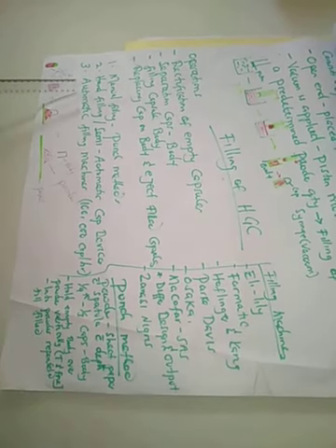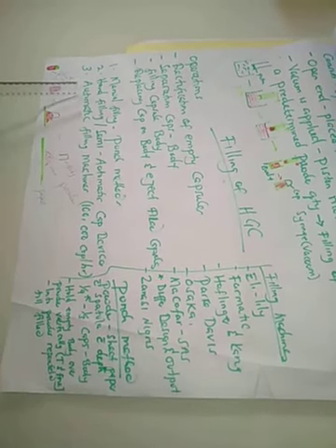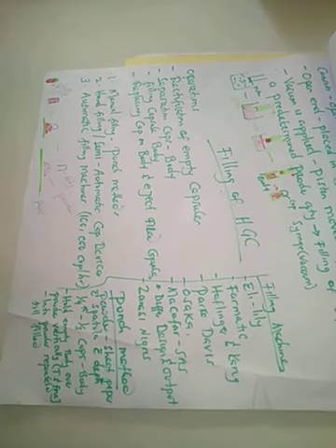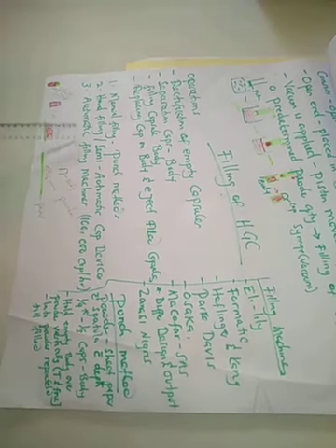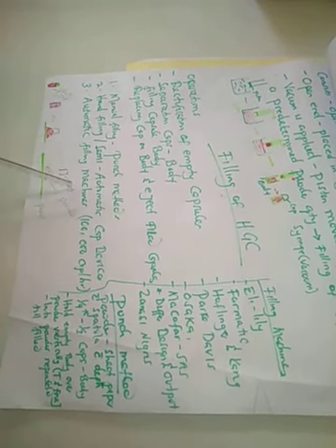So here you just introduce the capsules. The machine is automated in such a way that it is going to rectify, it will separate, it will fill, it will close, it's going to eject. So the machine is automated to do everything. For the automatic machines, for example, they can fill and eject about 100,000 capsules per hour.